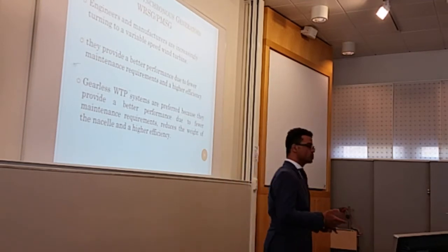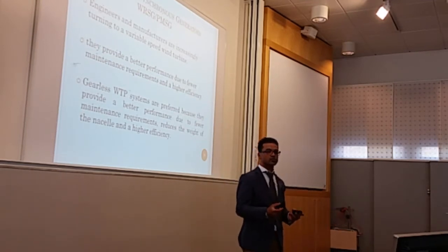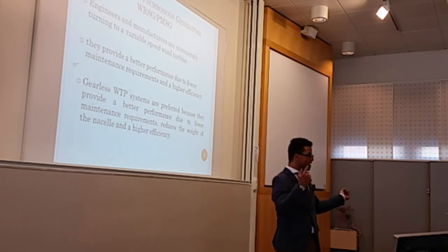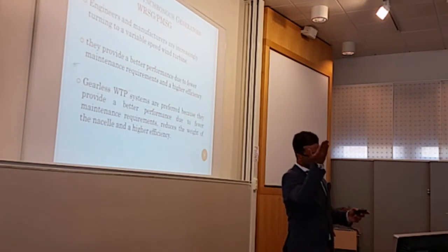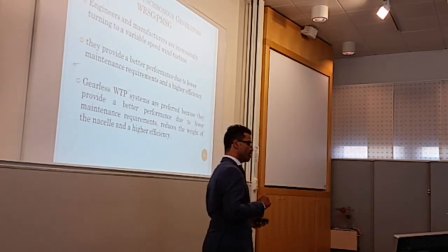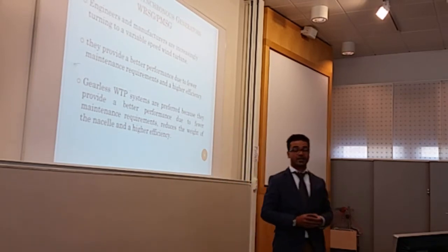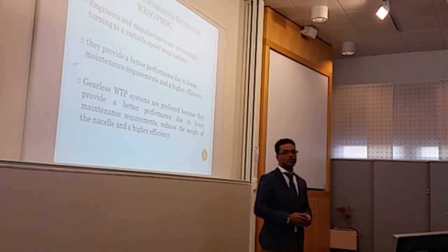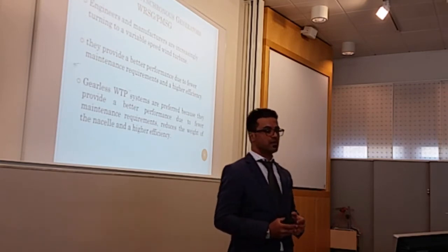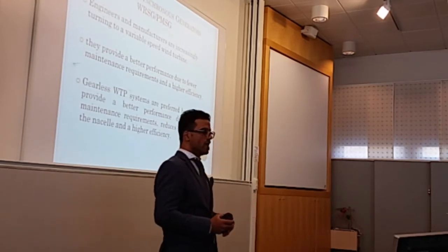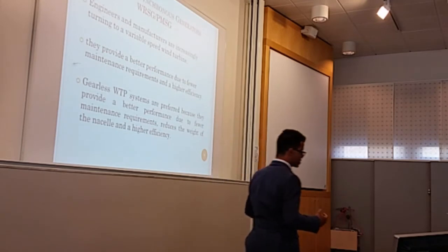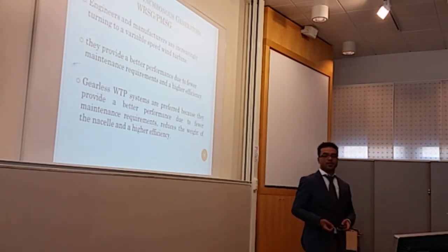What does without gearbox mean? Without a gearbox, we reduce some mechanical components connecting the hub and the generator, so we have already increased the efficiency, number one. Number two, we will reduce the weight of the nacelle itself. Number three, we will increase the reliability of the system, because something may happen or a fault may occur in the gearbox. So for these three reasons, the future system should work without a gearbox.